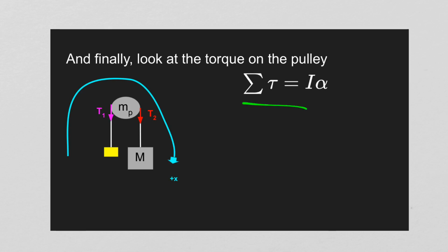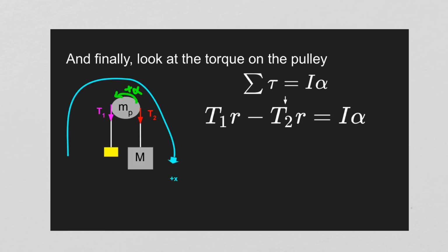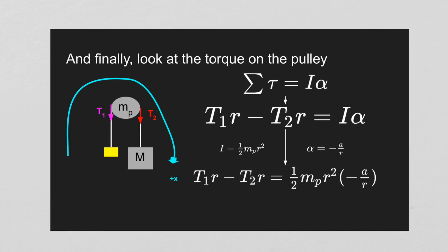All right, and I'm using a sum of torques equation because it's going to angularly accelerate. So I used my original condition. So I'll call this plus alpha, just because counterclockwise is positive. And granted, this goes counterintuitive, but I'll make that fix a little bit later. So a force, tension 1, at a distance, the radius of the pulley, minus T2 R2, because that's going in the opposite direction, in the negative direction of torque, causes the moment of inertia of that pulley to accelerate. So then I'm going to use what I know of the moment of inertia for a pulley, and I'm going to use alpha.